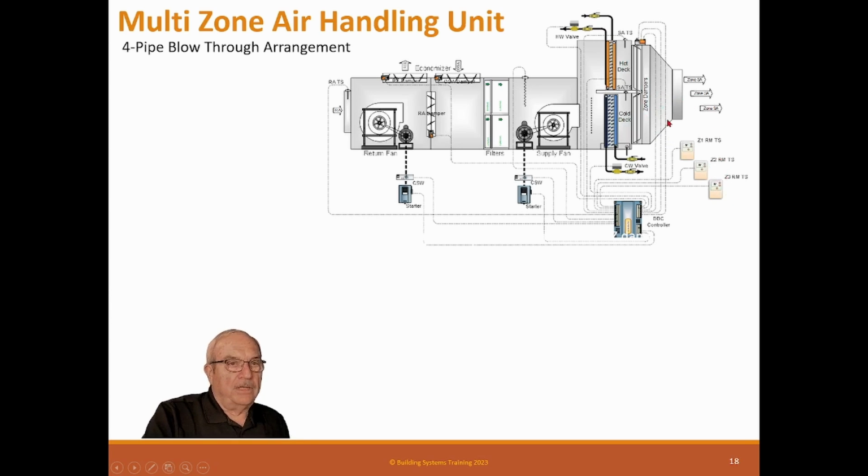Now, in my early days of doing design, I've had multi-zones with 11 zones. Man, you ought to try to design the duct. 11 zones leaving this unit. Some of your zones were 4 inches, 1 damper wide, so you had 4 inches wide.